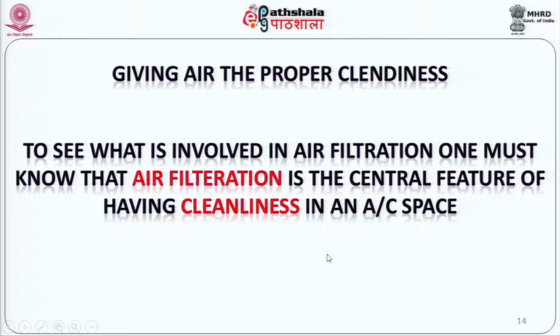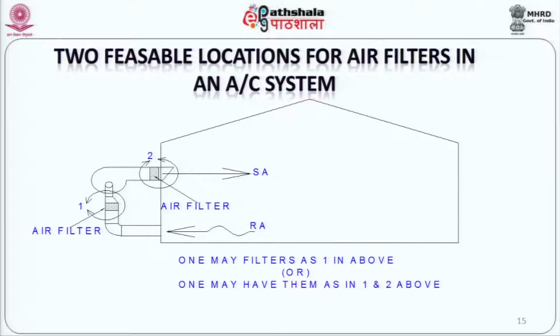So filtration is something which contributes to the proper cleanliness of air. Now, what are the basic locations of filters that one can look at? You can look at filters to be incorporated on an air conditioning device. This I would show as an air conditioning device. You could have a filter which can be mounted on the discharge end of a device, or it could be mounted on the suction end of a device.